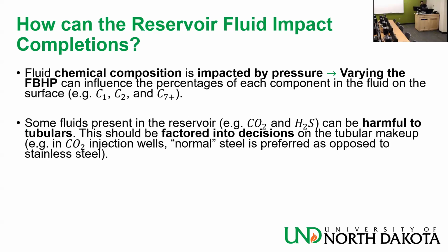Some fluids present in the reservoir, like CO2 and H2S, can be harmful to tubulars. This should be factored into decisions on the tubular makeup. For example, in CO2 injection wells, normal steel is preferred as opposed to stainless steel. Nowadays, because carbon sequestration is fashionable, a lot of wells are being drilled for CO2 injection, though not for sequestration reasons but for EOR reasons.